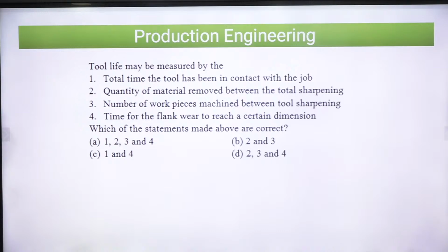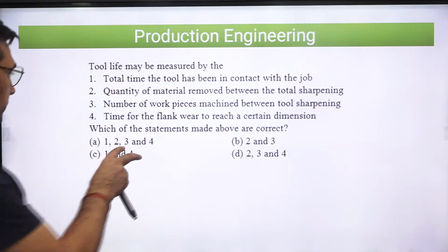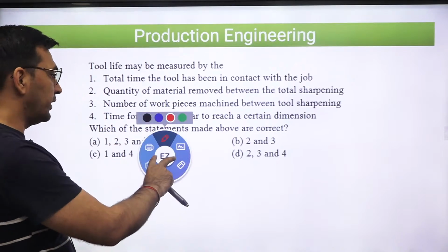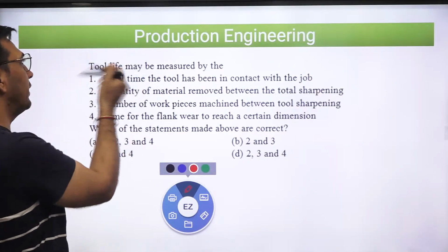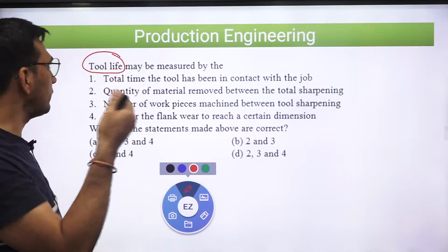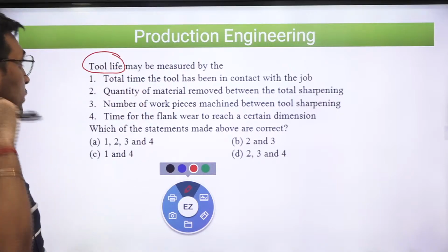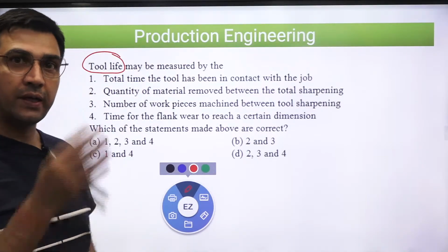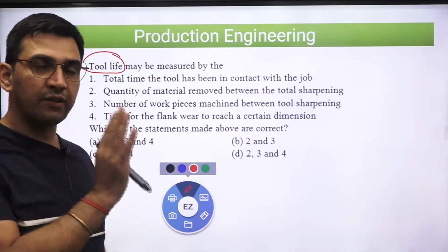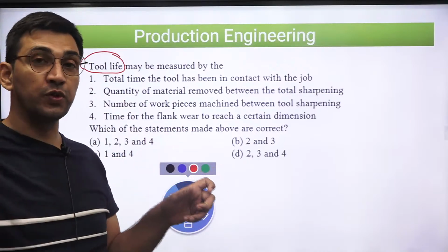Okay, I think it's quite good. So see, any of these methods I can follow for tool life. Tool life does not mean in terms of time. Tool life means when I'm using that tool, how many parts it can produce. Earlier, one tool, same material, everything the same, is producing 10 parts, another is producing 20 parts.